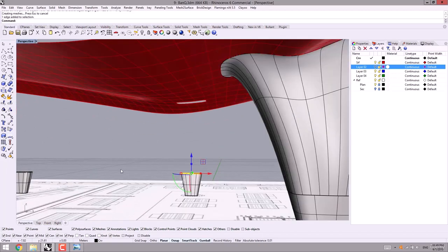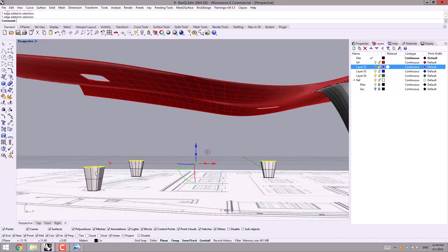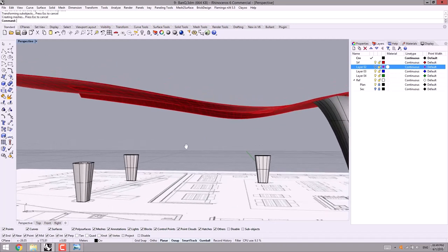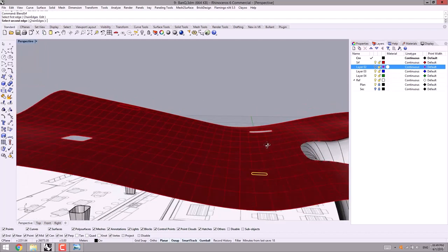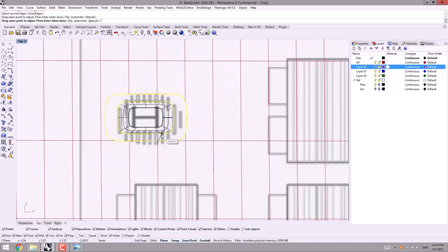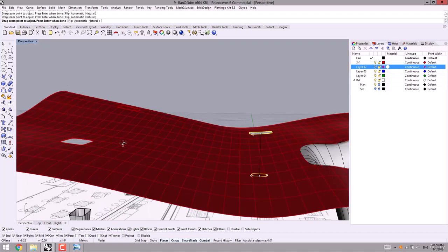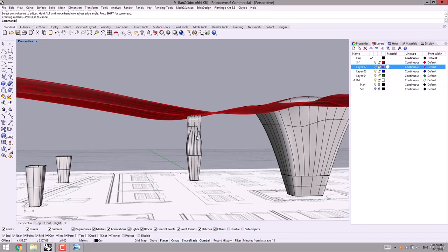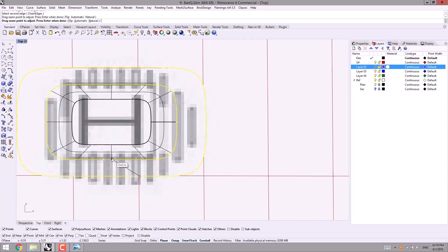However, I could have moved the curve or the edge surface upwards, but no matter, I can move the other ones. I hold down Ctrl and Shift and then I move the top edges. Check it out. I extend the columns, then blend surface, then I blend the edge surfaces. Check it out. At the top view, I adjust the seam points and make them aligned. Check it out by click and drag. Well done. And following that, by pressing enter, let me try again.